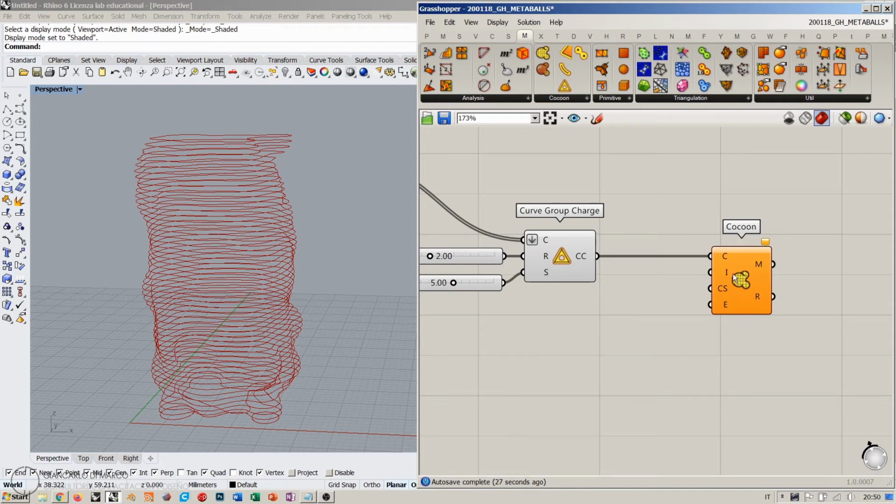Okay, so cell size regards the size of the polygons of the mesh. So the smaller the value, the higher the resolution of the mesh. I always recommend to keep this value high in order to create a low resolution mesh at first, and then eventually start decreasing this value little by little in order to not have your computer crashing.